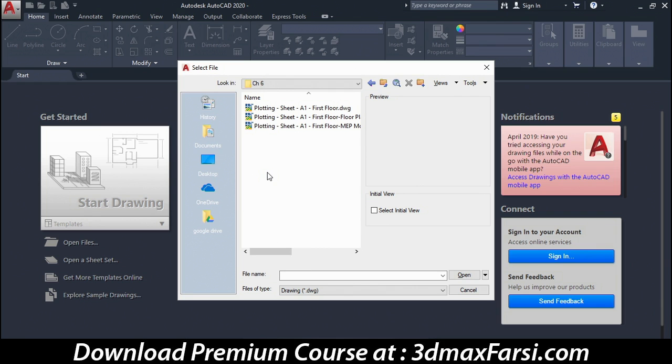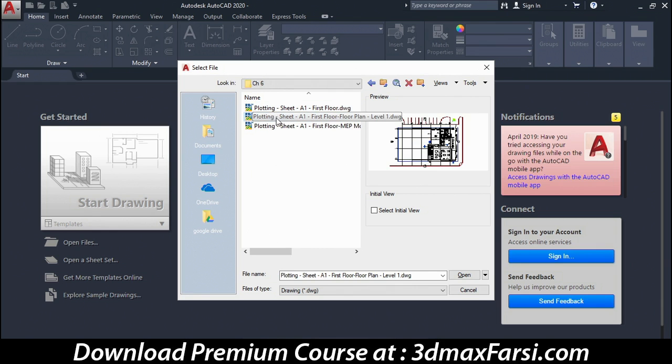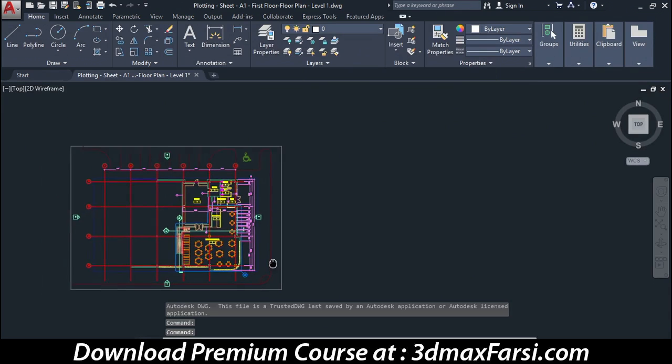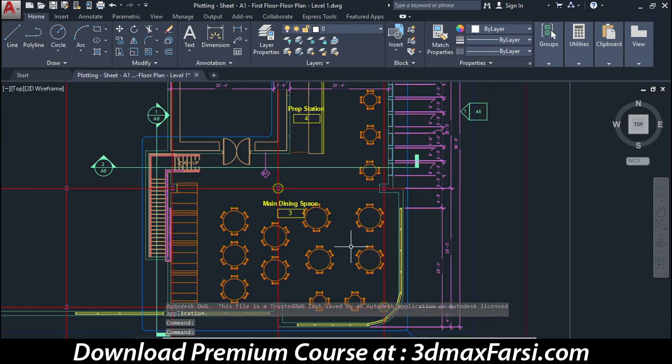So if you have a copy of AutoCAD, then you're welcome to switch over there and open the result. Now, even though I exported a single view from Revit, notice that I actually got 3 DWG files. So one of these is the actual title block, the other is the architectural model, and the final one is the MEP model. So I'll go ahead and open up the architectural model and click Open here. Now, notice that all of the information came in various colors. Those correspond to the various layers that we were using in that mapping table.